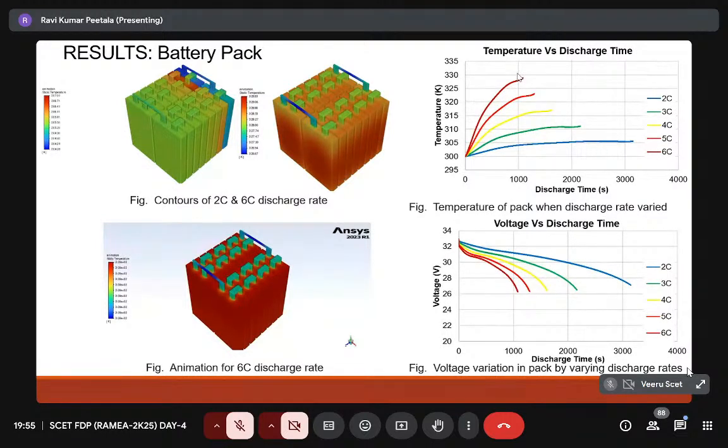After the melting temperature, maybe 80 degrees centigrade, let us say paraffin is 80 degrees centigrade, once the PCM reaches 80 degrees centigrade it starts melting. That melting happens as you increase the temperature and heat, and after that you have to remove the heat from the PCM also, right? Otherwise heat will be transferred backwards. So removing the heat from the PCM in the liquid phase is difficult and it is a slow process. If it is in solid, there is no issue. Am I answering his question, or does he have another question?